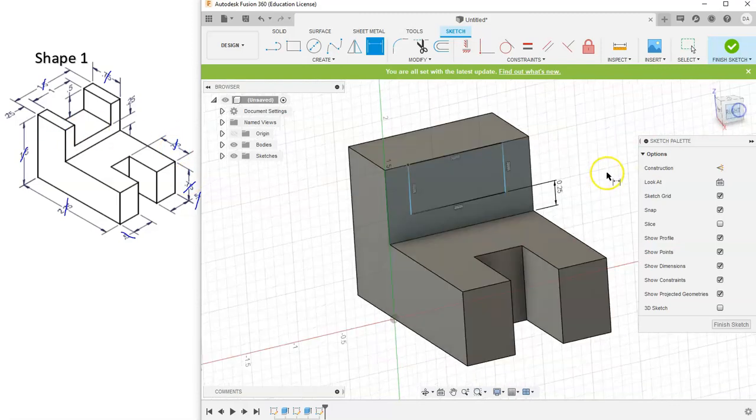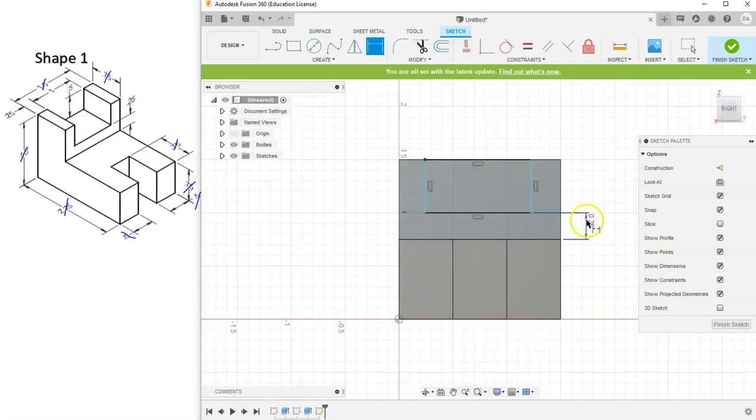It might be a little less obvious from the right side view, but I would like you to familiarize yourself with how to see it from the side view, how to rotate this in your mind to see what this would look like from the side view. So for example, what would be the dimension between these two edges from here to here? Well, if we follow these edges all the way to the end, we can see the extension lines coming out. It is clearly this 0.25.